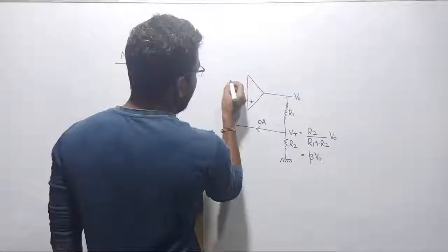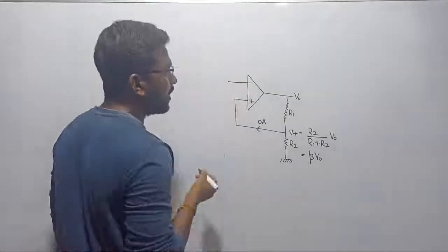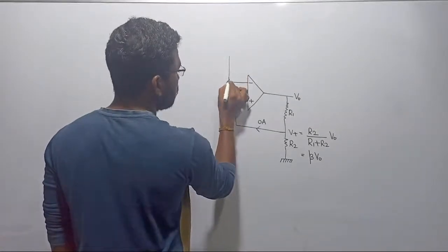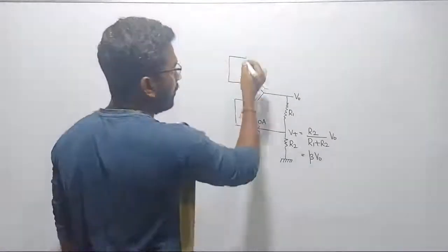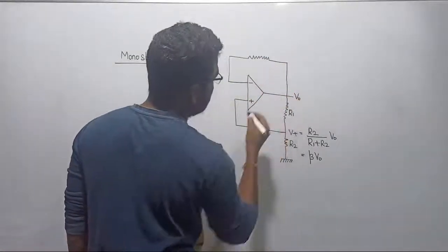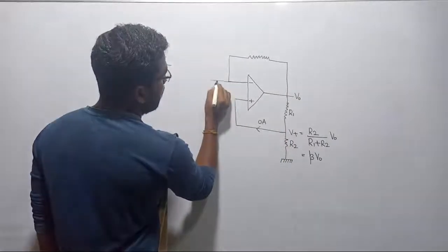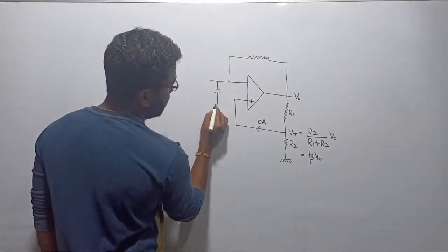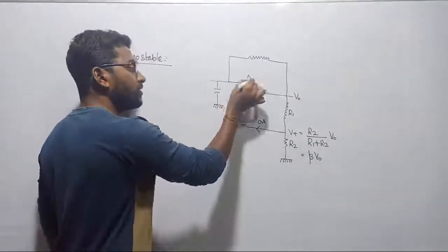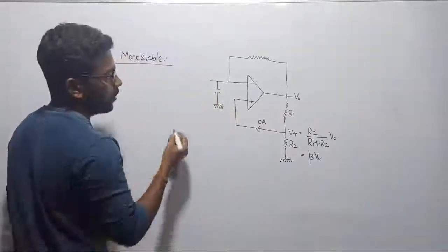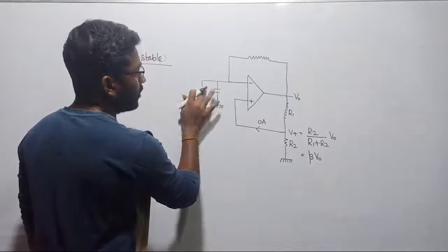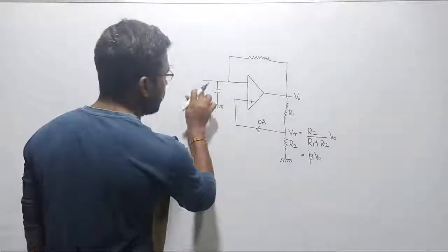Now let us come back to the other terminal, the inverting terminal. There also we are going to connect some components. Already we have done that operation, anyway let me repeat. Here we have some resistor, and then let me connect a capacitor. One plate of the capacitor is connected to the inverting terminal, and the other plate is connected to ground. Now across this capacitor I am going to connect a diode. That is our next task.